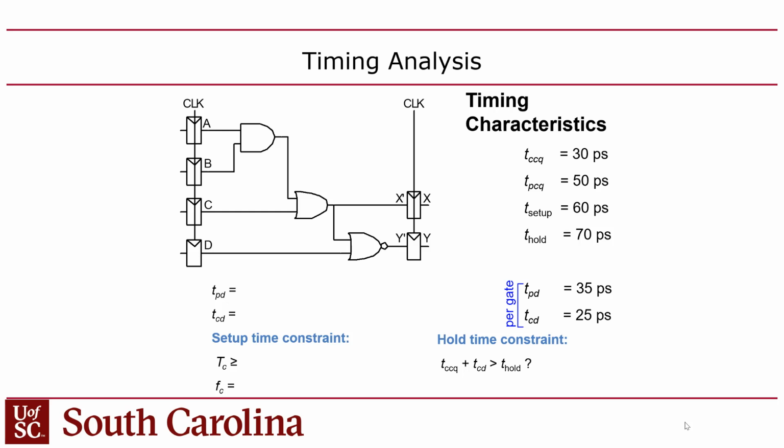But I may ask you a question on the exam where I may actually have different delays for each gate depending on what the gate is, right? Because obviously a 3-input gate is going to be slower than an inverter, right? It's just a different type of gate.